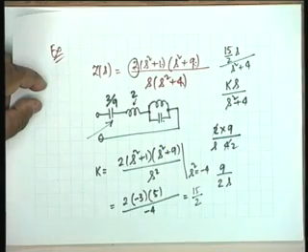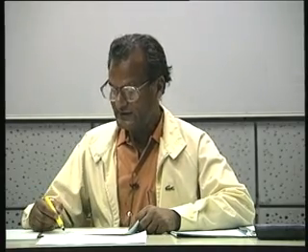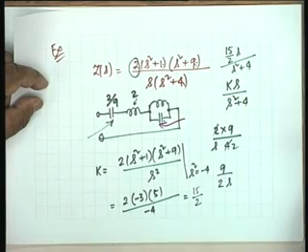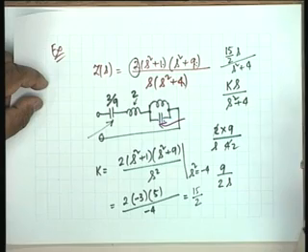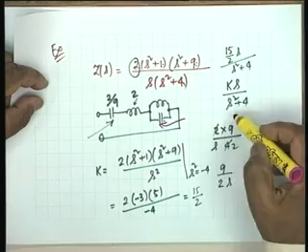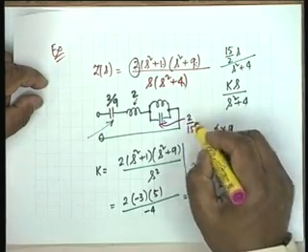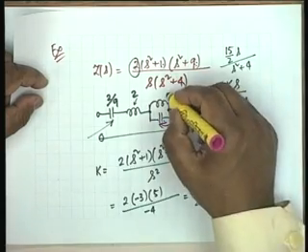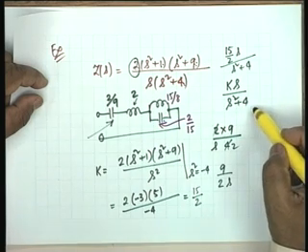This one, for example, the capacitor. So shouldn't that be the residue there? What is residue? So shouldn't that be the value of the residue? No, k is not residue, k is twice the residue. Residue is half of k. So the capacitance value is simply 1 by k, not k, because this is an impedance. You see, it would be s by k. So capacitor value would be how much? 2 by 15. And the inductor value? 15 by 8. I hope you are right. 4 into 2 divided by 15.